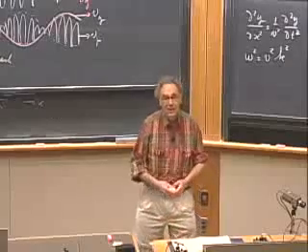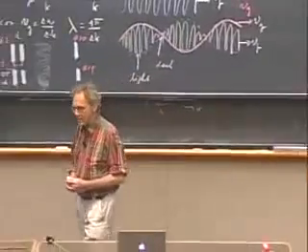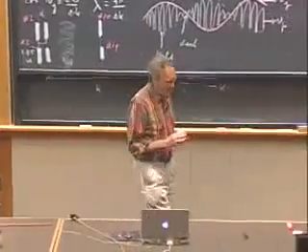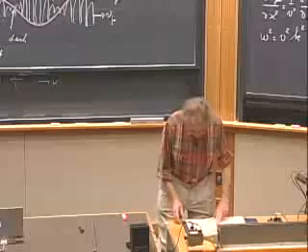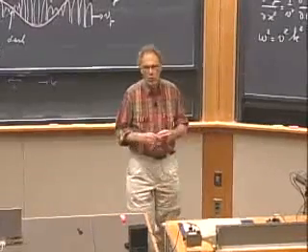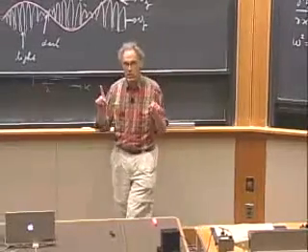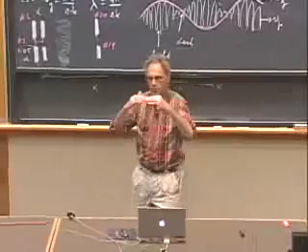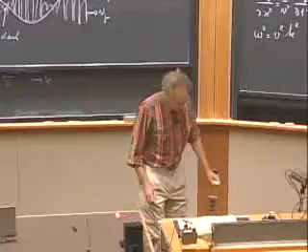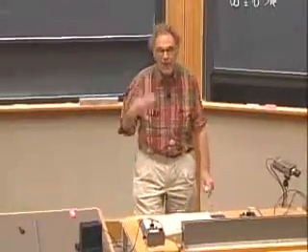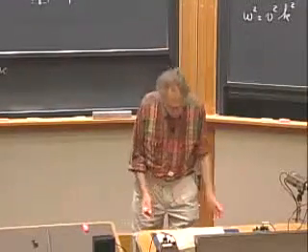However, there is something that we did not take into account, and that is the stiffness of the wire. Imagine for now that the tension is 0. So you take a piano string, or the string from a violin, and assume there is no tension at all. And you take it in your hand and you bend it. There's no tension, you just bend it. It wants to straighten out. And that's the result of stiffness. And it is due to the stiffness that you get an extra restoring force, which we have ignored. We didn't take that into account.